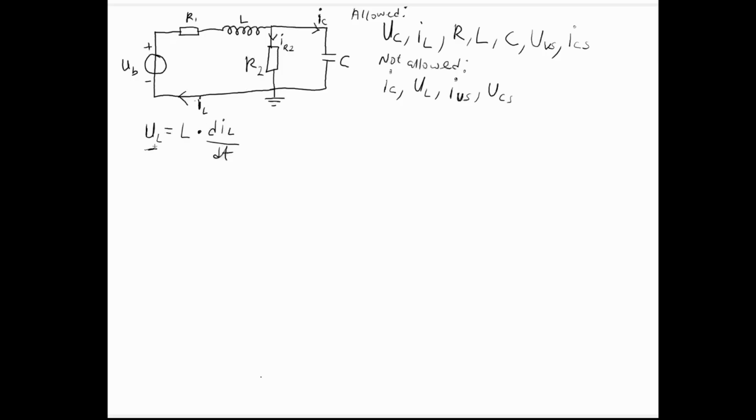As I said, because there is a voltage on the left-hand side, I'm going to use KVL, or the mesh current analysis. So I will make use of this loop, because the inductor in question is on this loop, and I'll call it the first loop. So loop 1 or mesh 1. Now, I start from here, going along the direction of the current.